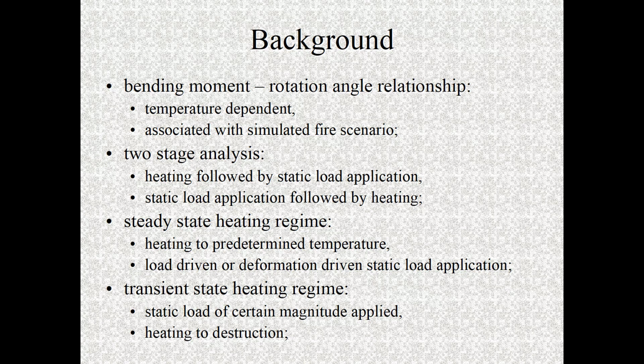In the first case, the structure is heated to the predetermined temperature and then loaded statically to the destruction, while in the second one, the procedure is executed in reversed order. That means the structure is statically loaded to a given level and then heated to destruction. In our numerical simulations, the destruction would be considered as a failure to converge to an equilibrium during an iterative increase in the load applied to the model.